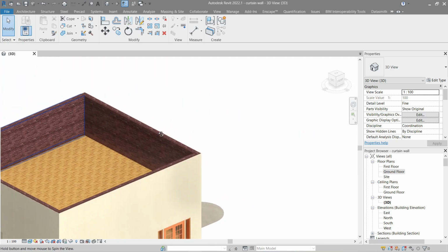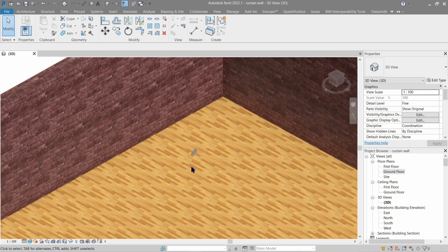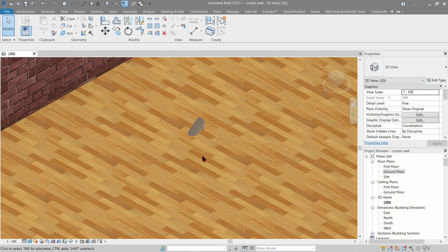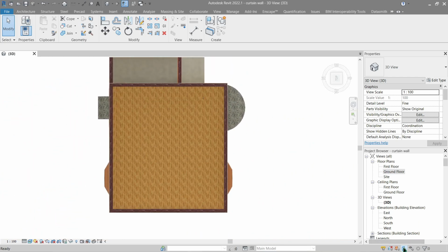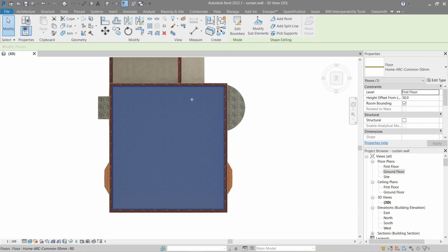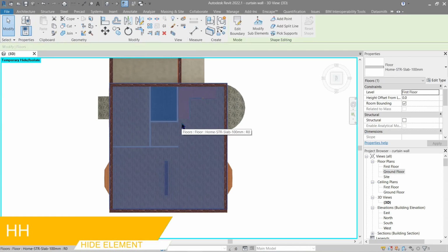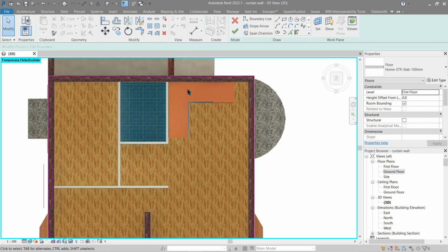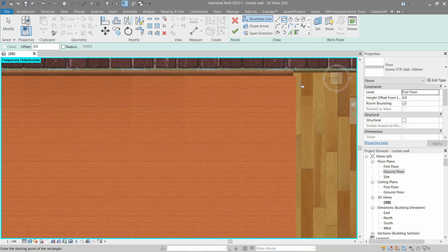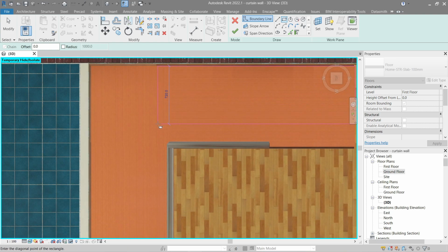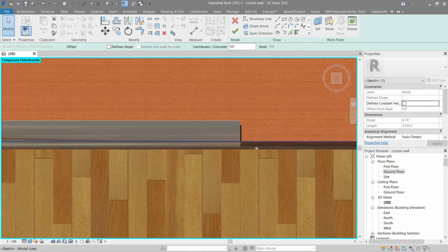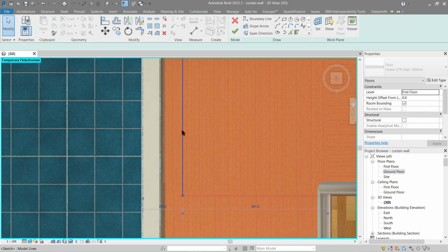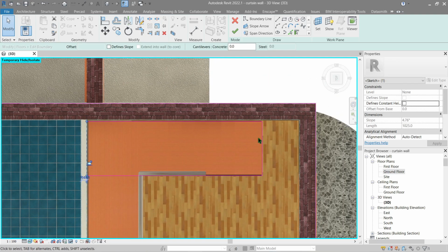And lastly, in this part, we have the stairs, right? Look at that. The railing is protruding until the first floor level. So why don't we go ahead and fix that? We can do it here in 3D. Click the top here, this one, click here. Let's temporarily hide this for now. And this one, edit boundary. Simply click here, so we have a rectangle sketch, and just align here like this. Same goes to this level. There, that should be good enough.